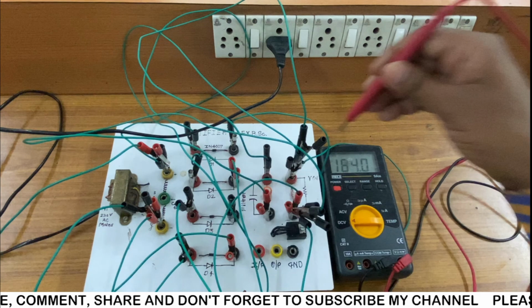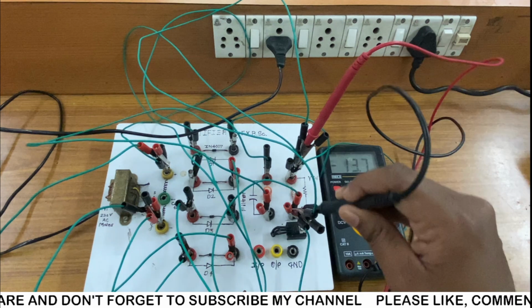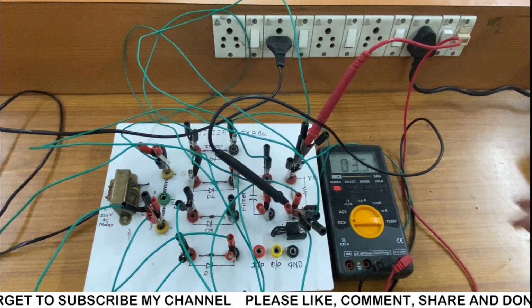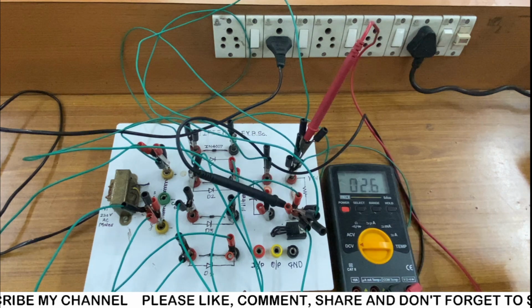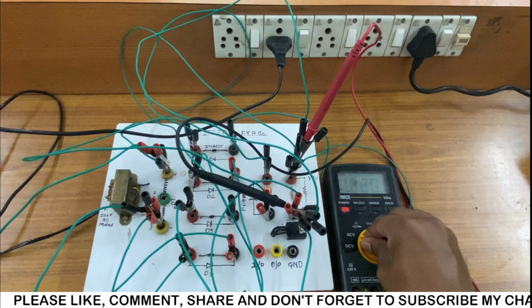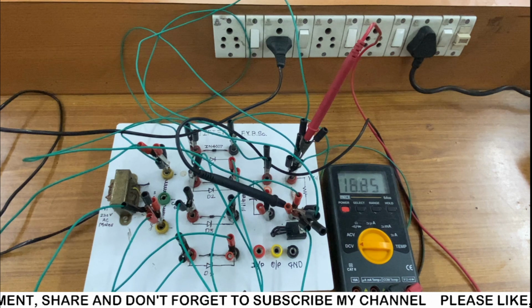What we are going to do, we are going to measure the ripple factor of this bridge rectifier. So let's look in here. We have to measure actually AC and DC. So first of all, we are going to keep the circuit on and measure the AC. So I'm going to measure the AC first. It is again indicating some reading of 0, and I'm going to go for DC, 16.83.